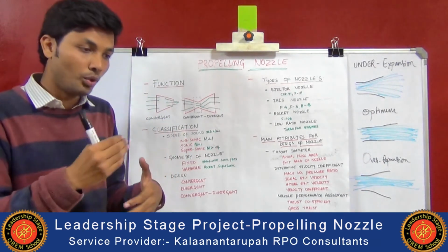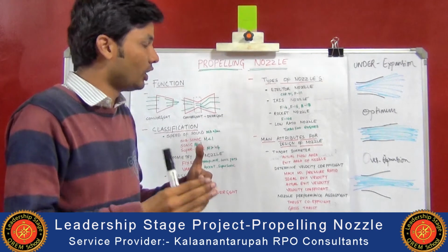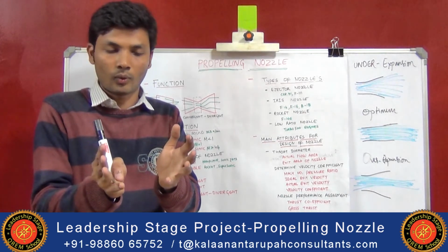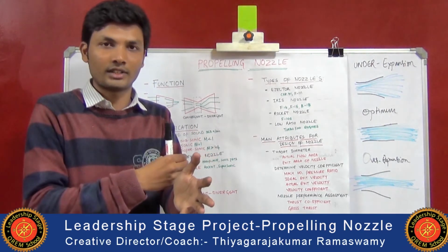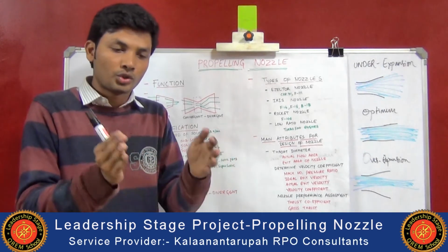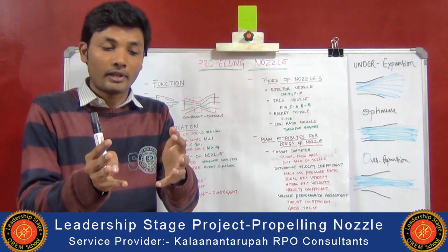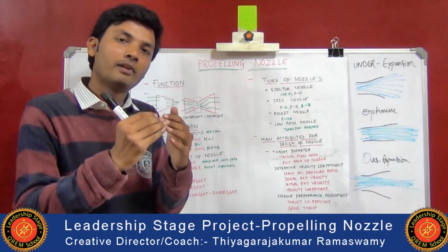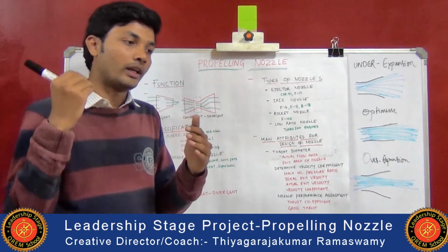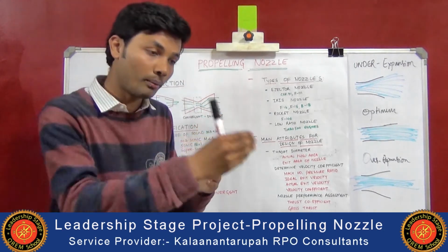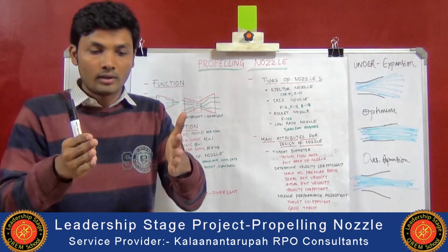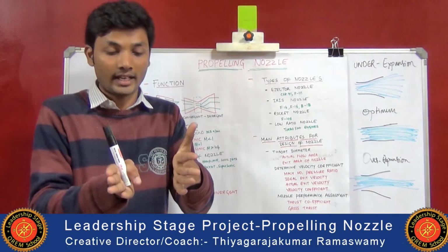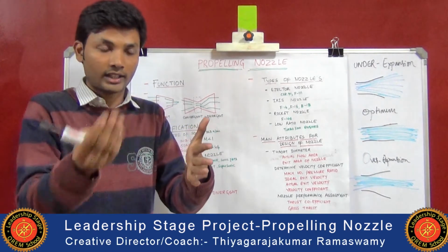If the back pressure is more, more energy is required for the engine to run in the jet engine. So the ejector nozzle helps to vary its diameter. First it will maintain one diameter where the expansion is more and it requires less energy for the engine to start, and once it achieves speed, the diameter will vary for the actual exhaust gases of the engine. Slowly, when the speed of the aeroplane increases to a certain limit where it requires some more thrust to go into orbit or its path, the whole nozzle will get dilated and form a convergent-divergent, and then the afterburn operation will start, which I already explained.